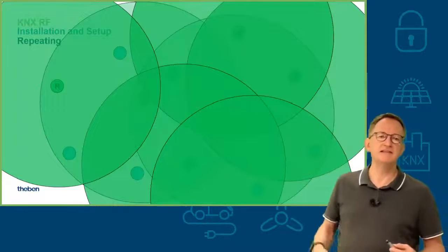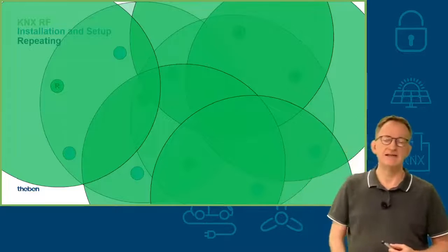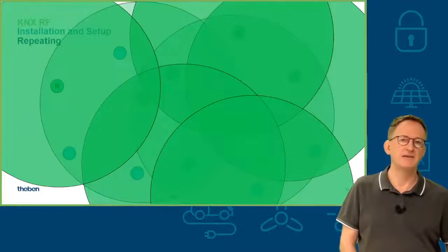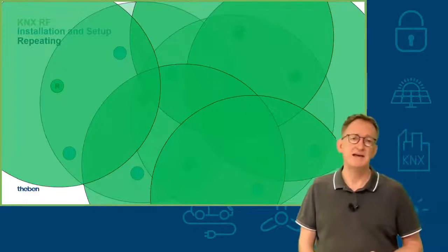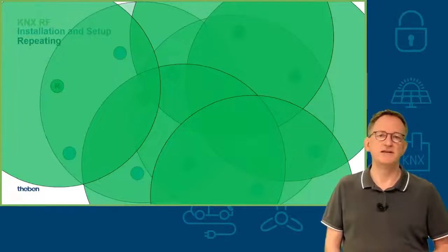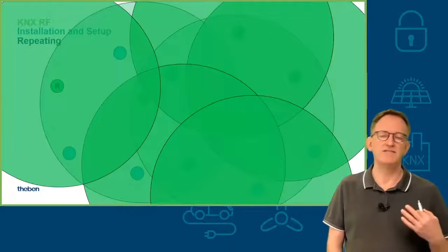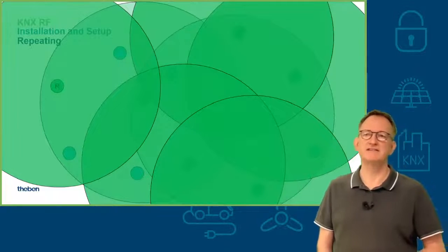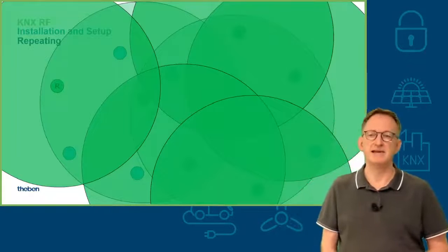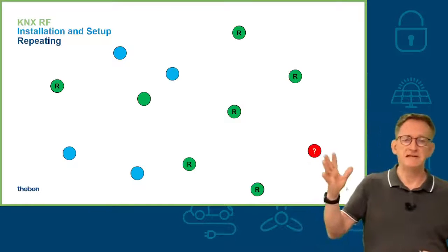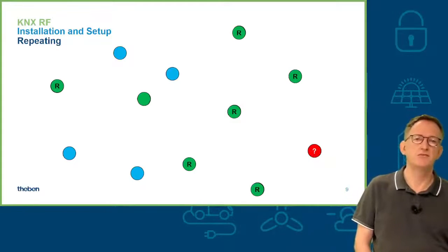So now we have a good signal definitely here on that, but the signal is always aborted or with collisions and so on. So it's never ever a reliable communication. So that's the reason why it isn't a good idea to set many devices as a repeater. Just set one device which is really in a very good position and use it as a repeater. So never ever set too many devices to enable the repeating function. You never know what will happen if you have so many repeaters.